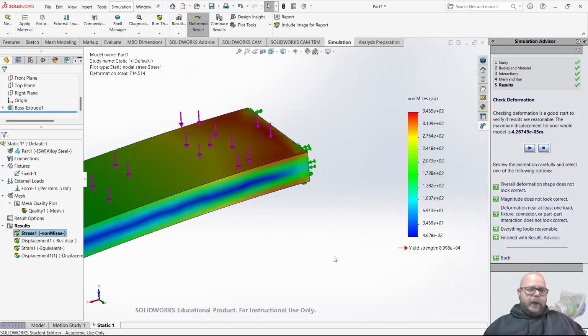how effectively a ratio, how much over designed are we? In this case, it's ridiculous. It's a safety factor of 260. This thing is 260 times stronger than what it needs to be to survive the load in this application. That's a ridiculous safety factor. Usually, sort of conventional wisdom in mechanical design is we want to shoot for something like 3, right?